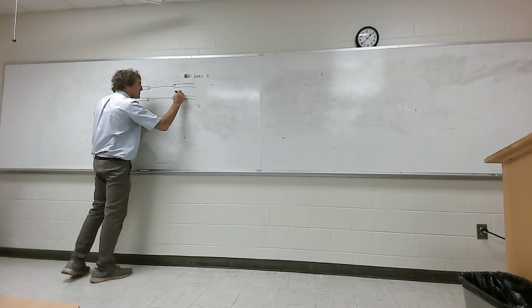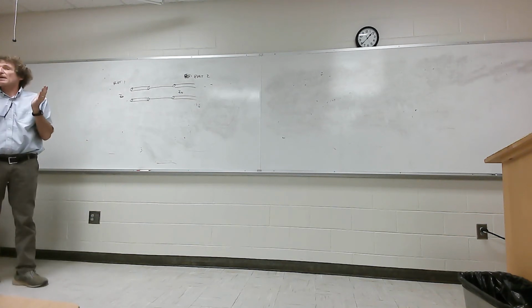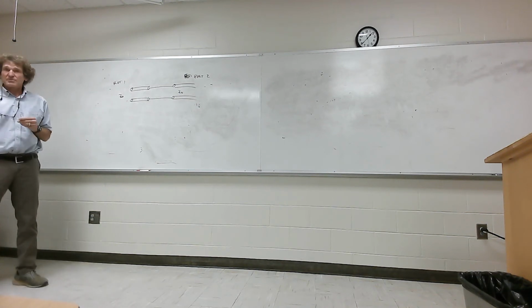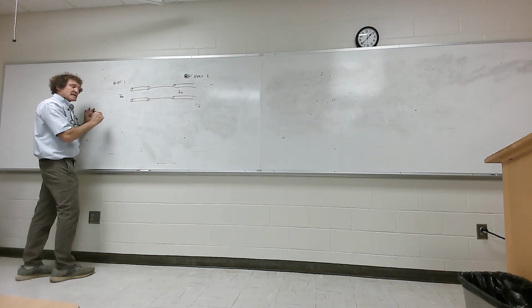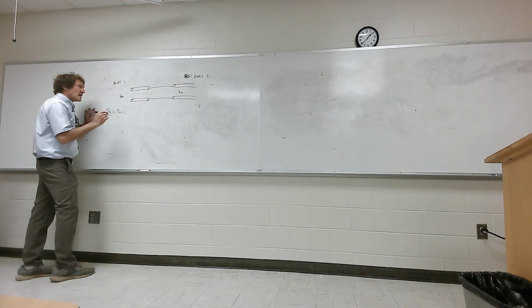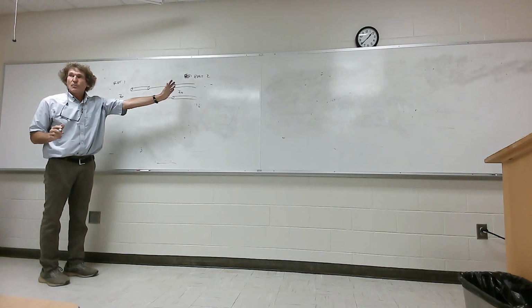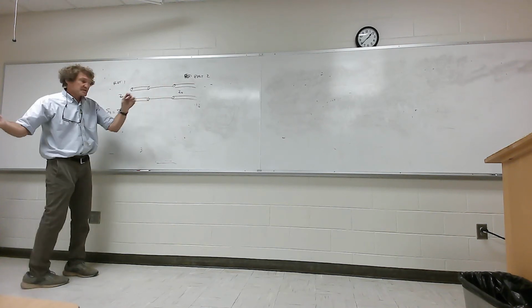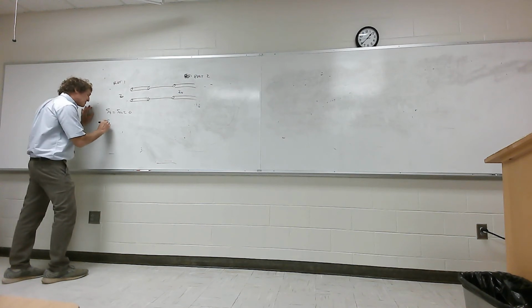Now just hear me. First of all, is it a reciprocal network? Does it look the same either way? Yes. Don't even bother doing S times S. It's a waste of time. Next thing is, what's the reflection coefficient of port 1, which will be the same at port 2? Just look. I'm coming from Z naught. Where am I going? To the same thing. What's the reflection coefficient? 0. That's a no-brainer.